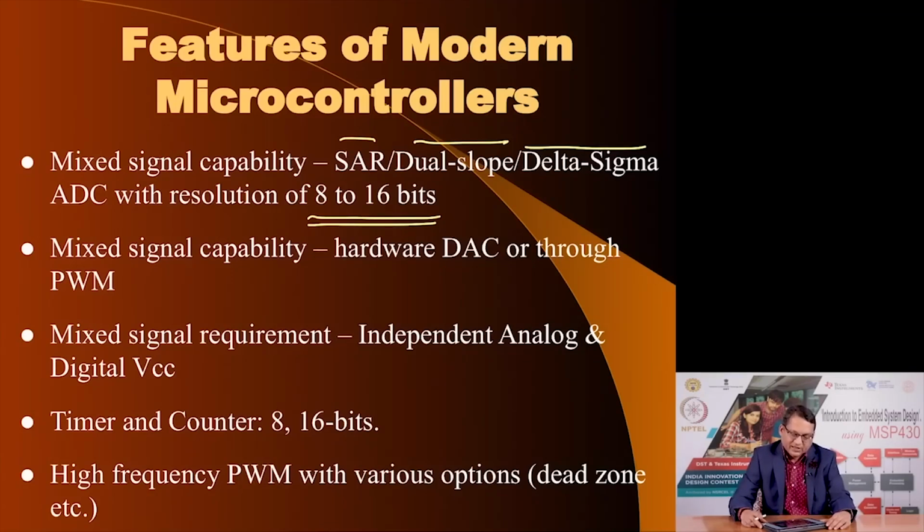As part of the mixed signal capability, a microcontroller may offer a hardware DAC, meaning it has an integrated digital to analog converter. You simply load a number into it and the DAC will convert it into a corresponding proportional analog voltage.